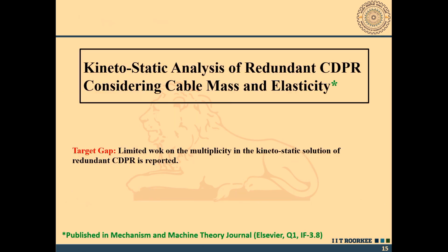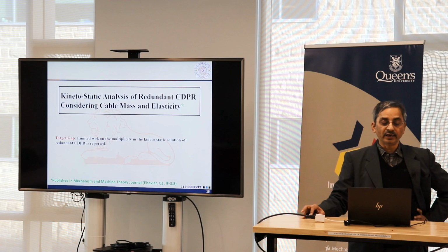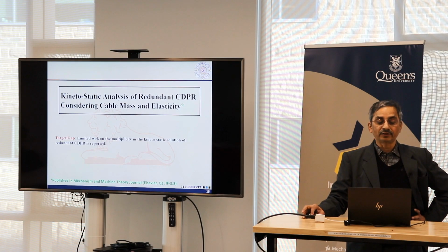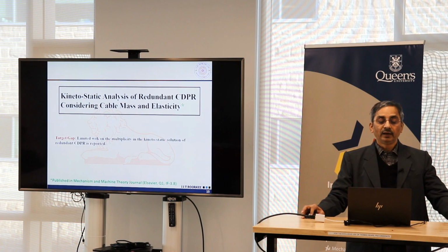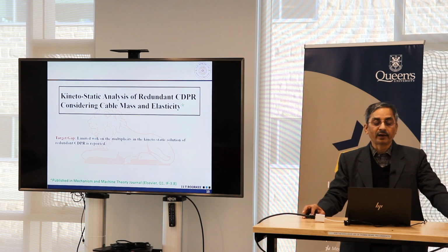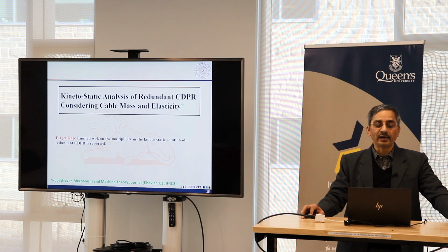So, I will be talking about a few topics only. The first one is the kineto-static analysis of redundant cable driven parallel robot considering cable mass and elasticity. We targeted a gap that limited work on the multiplicity of the kineto-static solution of a redundant cable driven parallel robot is reported.